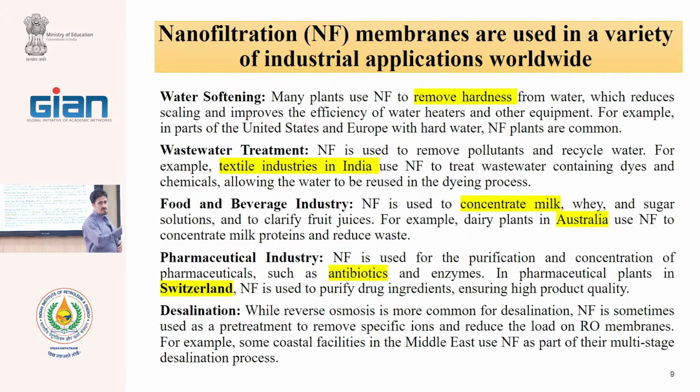But for seawater we use RO directly. In this case, because NaCl concentration is low, usually NF membranes are used that have higher flux and need lower pressure and lower energy. But the most application is hardness removal, which in many European countries is a routine process.